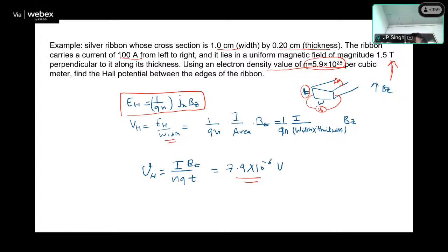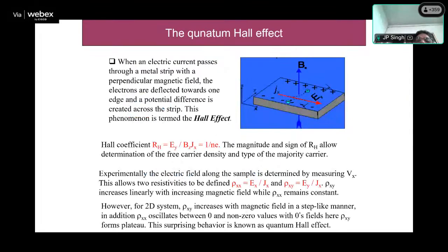One can see that. Now, because of time, I'll skip that part, or maybe continue, and another part, the magnetoresistance, I can continue tomorrow. So basically, whatever we have learned was the normal Hall effect, where we determine the Hall coefficient for this geometry, and because the charge carriers are deflected by the magnetic field, we get the Hall voltage generated across the width.